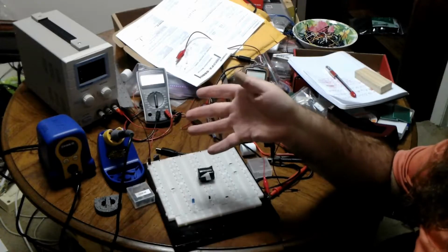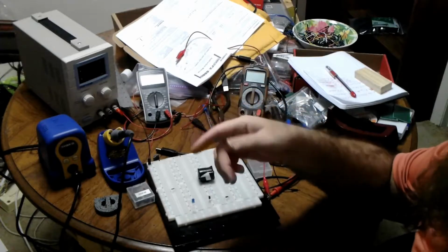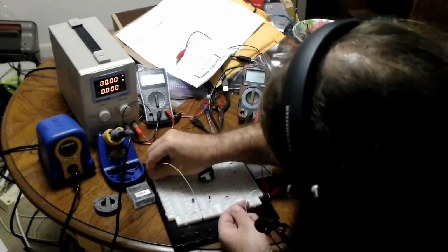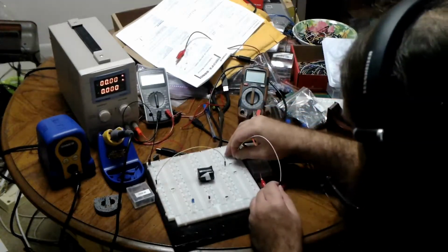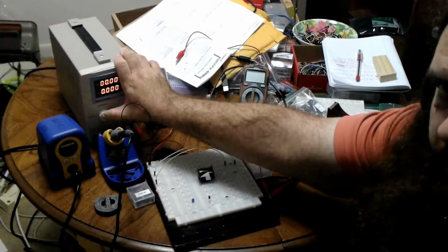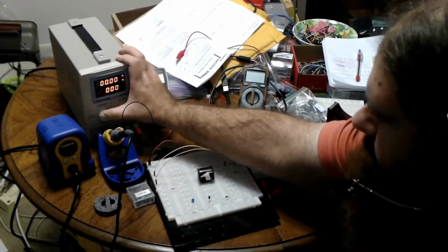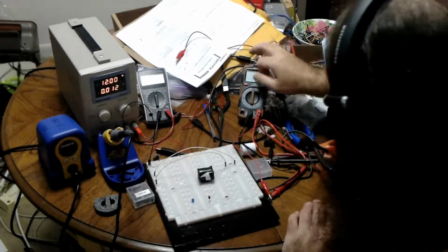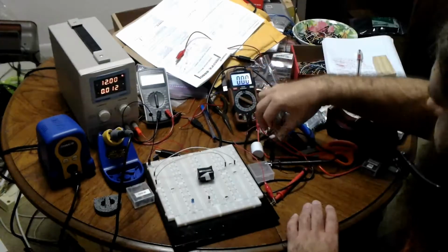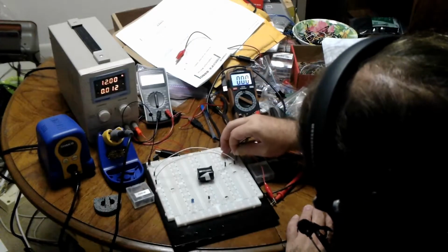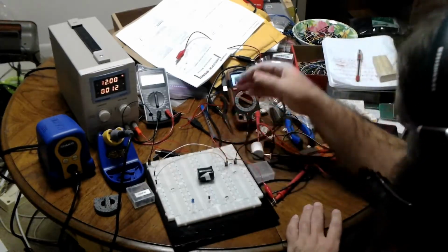So let's say I have my messy table and on it my power supply, currently set to 12 volts. So let's just connect these 12 volts through a 1 kilo ohm resistor and back over. So 12 volts divided by 1000 ohms should be 12 milliamps. And if I plug it into the correct hole, that's what we get. So let's go ahead and measure our DC voltage. So I'll set it on the 20 volt setting. I'll measure across the resistor, and unsurprisingly, we get 12.